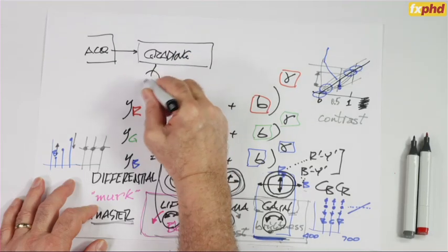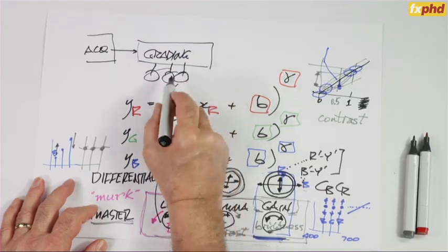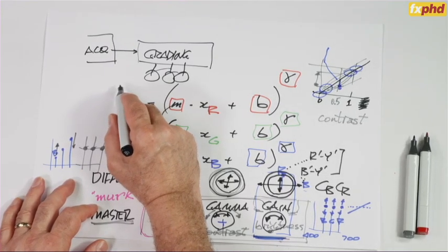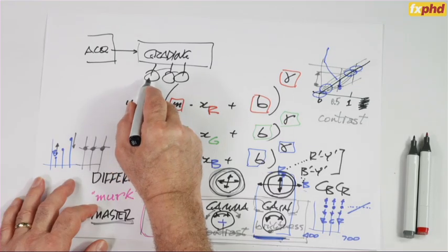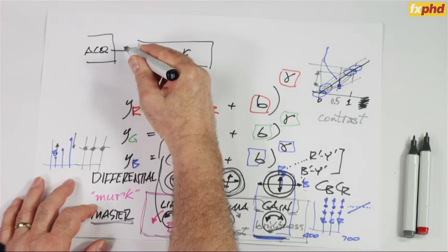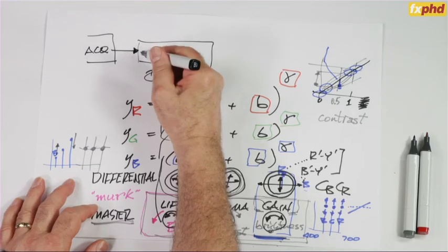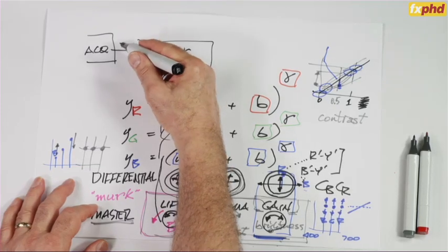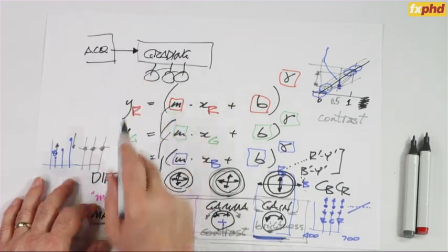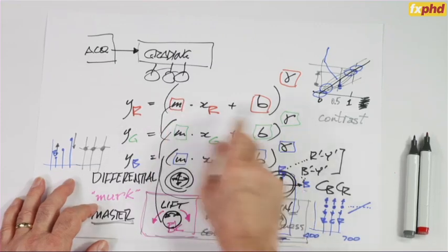We want to make adjustments here, some of the adjustments are to dial out errors that were made. Some of them are to deal with technical issues like what coding scheme did the data arrive in. You know, was it studio range or full range, for example? Those sorts of adjustments can be accommodated by these controls.